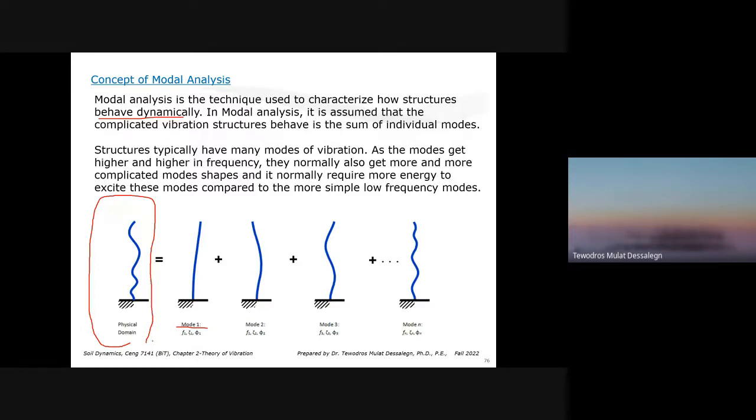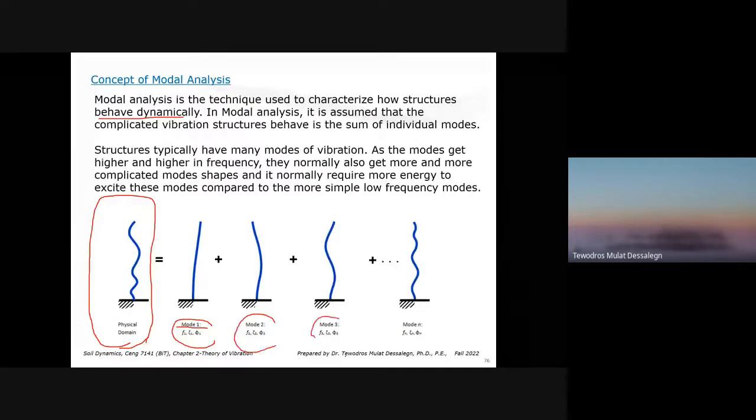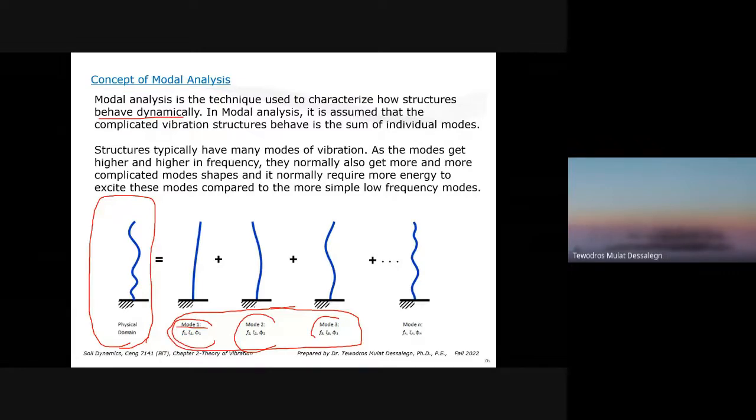So in modal analysis, usually you're not getting the stresses or things like that. You are getting the mode shapes. What's the first mode frequency? What's the second mode frequency? A third mode, a fourth mode. After a few modes, we're not that interested because higher modes are not that significant to excite. But the first, second, and third modes are significant in terms of response. I'll show you later in a successive chapter. Even for a soil column, we'll see how the modes look.